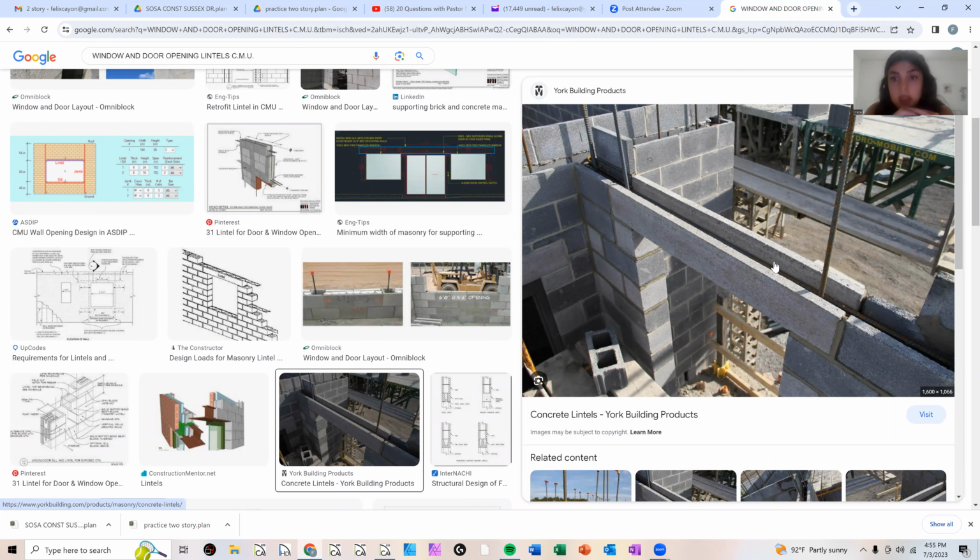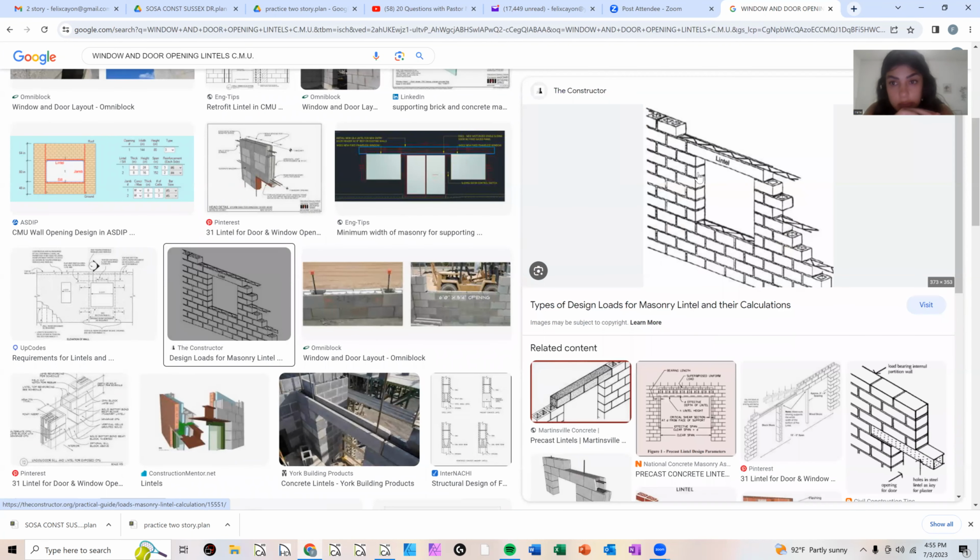Okay. And then on top of that goes the bond beam. This is an example. So this right here is a bond beam. This gets filled with concrete as well. The lintel is like a bridge across every door, garage doors, everything, regular doors, they all have lintels. This is like a bridge that gets a piece of rebar inside of it and it's filled with concrete.